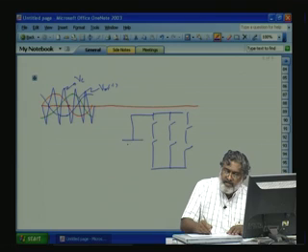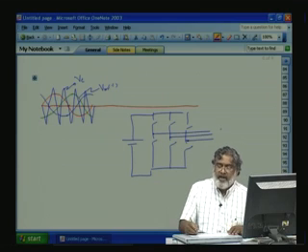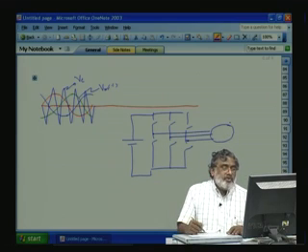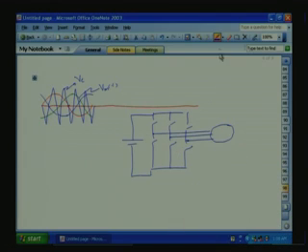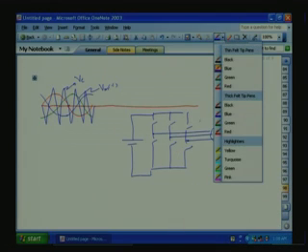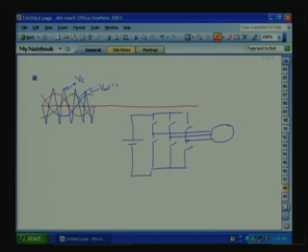You have the VDC and 3 loads like this. Let us say that if it is for the motor, it is motor. So, for the ABC phases, depending on when the triangle is greater than the sine wave, the top switch is on. When the triangle is less than the sine wave, we will be using this one.